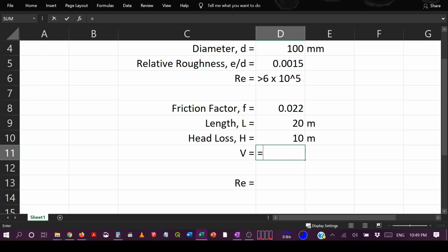For square root, I cannot simply write square root. It doesn't mean anything. Excel has some commands, that is SQRT means square root. Now you can see below where I'm typing, it is already giving us some suggestions. So SQRT is actually a formula which is available with Excel. So I'll put bracket, and it suggests how to use this formula, SQRT, then within bracket put the number, and instead of number we are again going to put another formula. That means a formula inside a formula.